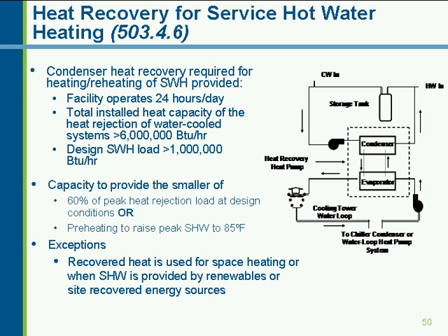And this requirement comes into play if you've got a facility that operates 24 hours a day. If the total installed heat rejection capacity of water-cooled systems is greater than 6 million BTUs per hour, and the service hot water load is greater than 1 million BTUs per hour, this is required.